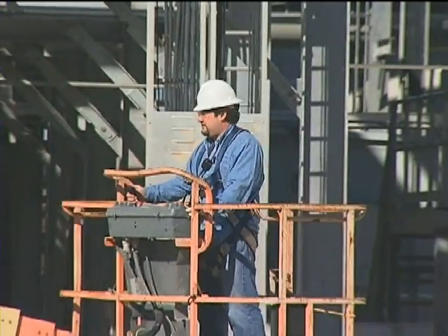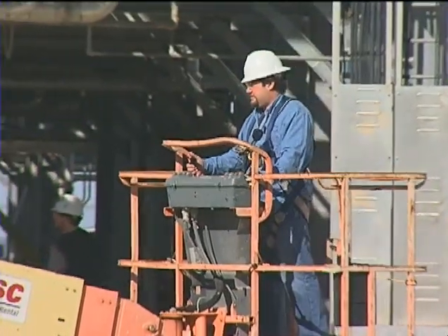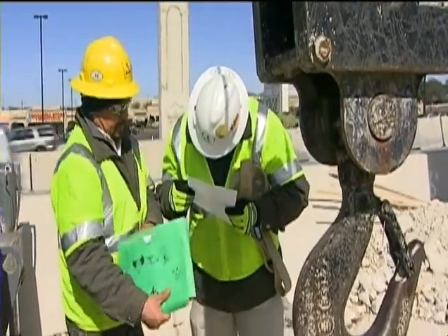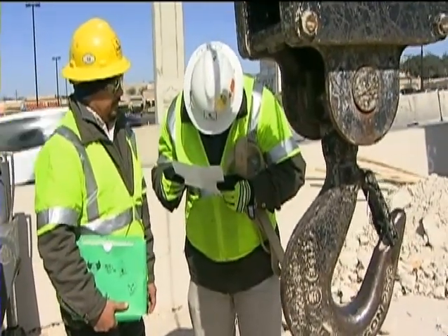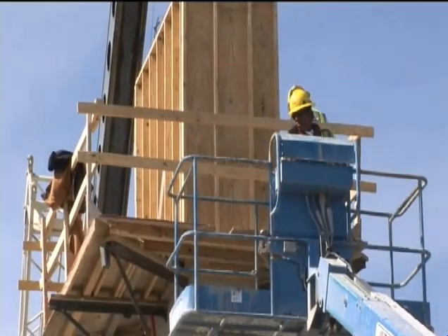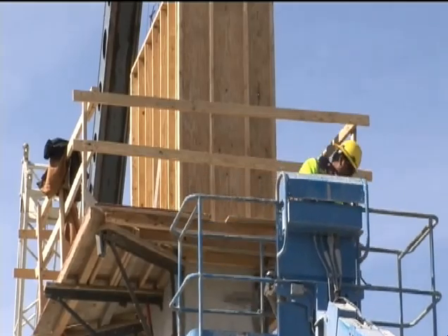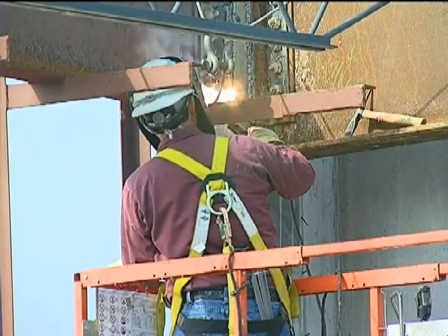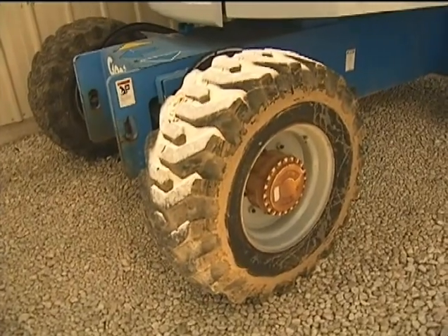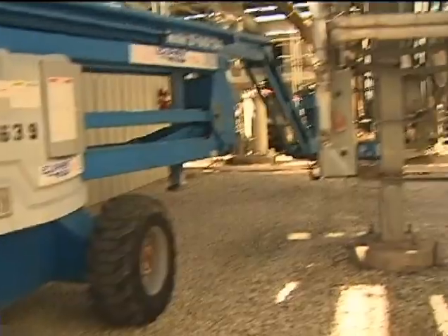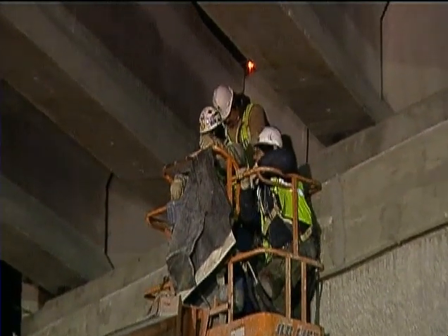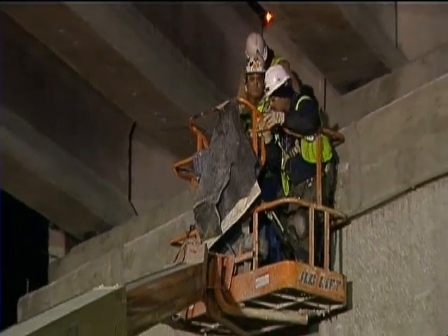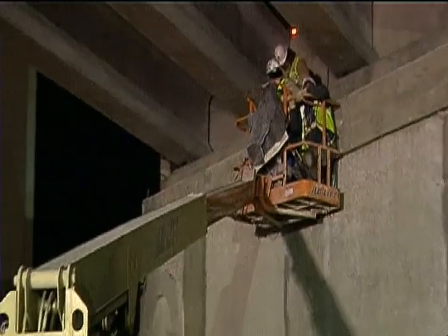When selecting a lift, there are many important issues that must be considered. Among these issues are the type of work being performed. Examine all aspects of the job prior to selecting a lift. Choose a lift with the requirements in mind. Does the work require compressed air, electrical outlets, water supply, racks, welding support, etc.? Examine the ground terrain where the lift will be operated. Is it level or not? And finally, determine the number of employees that will be using the lift. Make sure that the number of employees never exceeds the weight capacity for which the lift was designed.